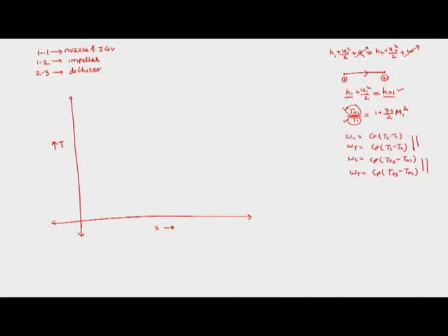The difference between those two formulas is just that we are considering the kinetic energy. So when we replace the static temperature by total temperature, we have started accounting the kinetic energy. Similarly, when we considered the pressure ratio, we had considered P2 by P1, which is the pressure rise in a compressor. But here, while dealing with the components, since we have to find out their efficiencies, we will deal with the total condition instead of the static condition. So our pressure ratio Rp will also be P02 upon P01.